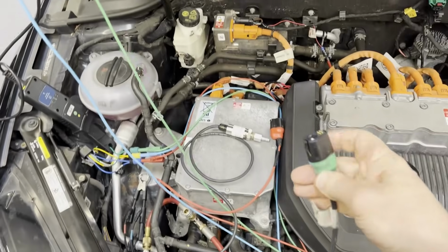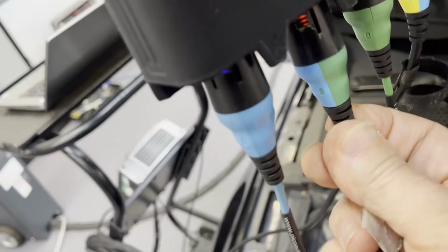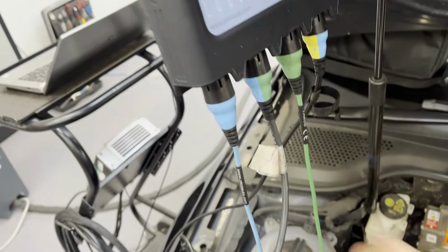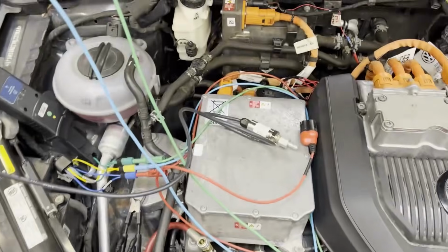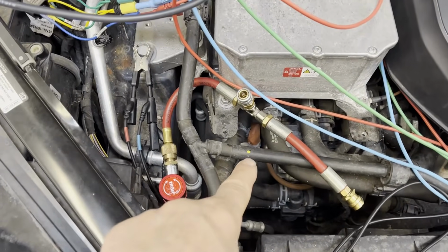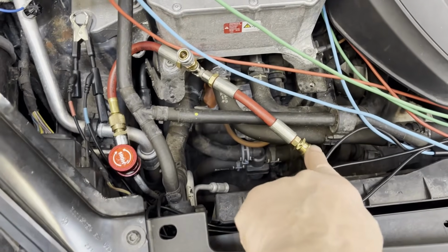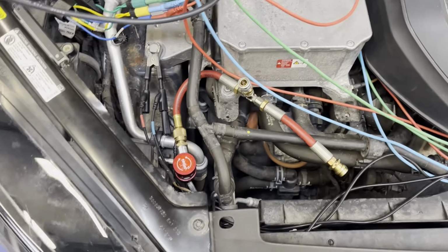We are now going to connect the BNC Plus pressure transducer to channel B. Okay, we can then apply the pressure transducer to our pressure tap here, then close the tap. We're sealed at this end, so there's no risk of gas leakage.